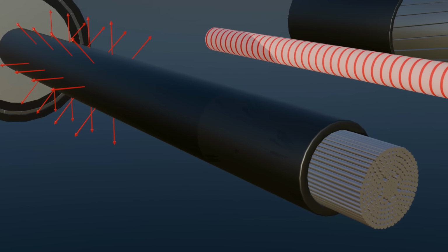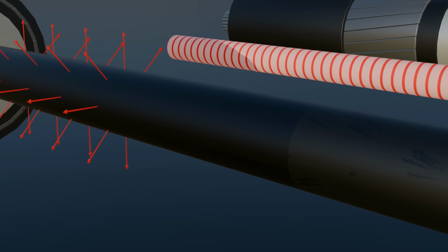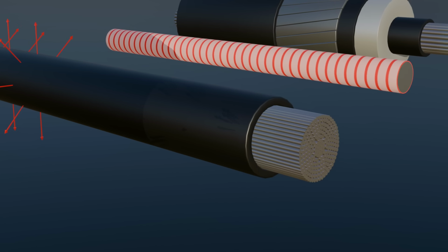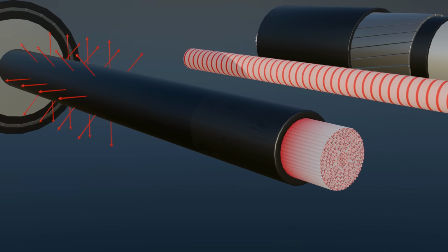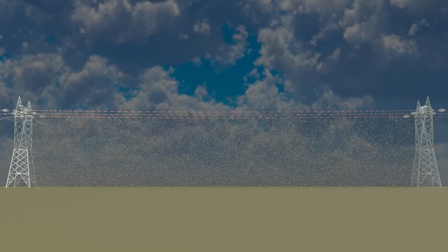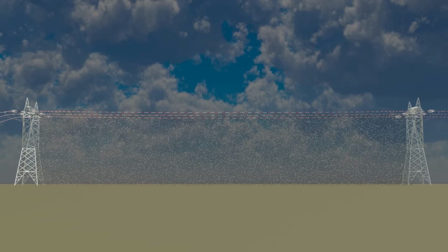One important point must be understood here. The safe voltage limit is not decided by the conductor alone. It is mainly decided by the insulation system around it. In an overhead line, as the voltage increases, the conductor is placed higher above the ground. This allows air to act as proper insulation between the conductor and the earth.